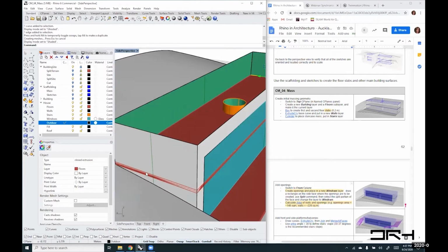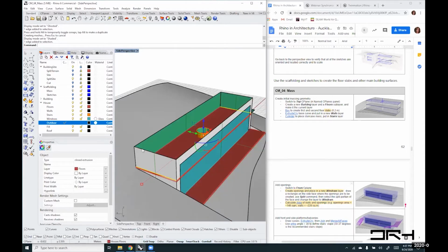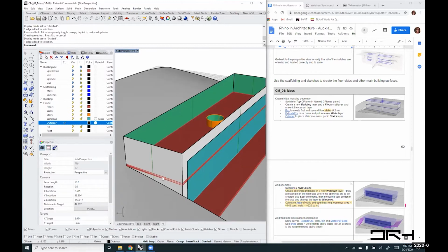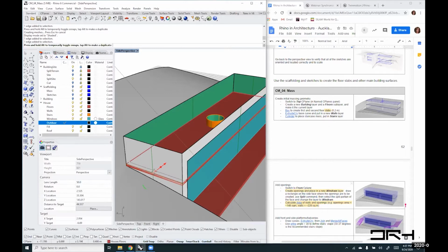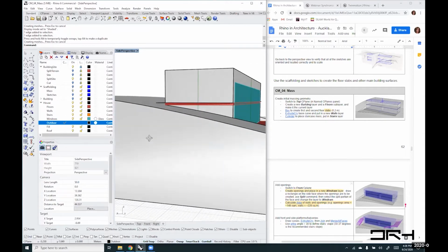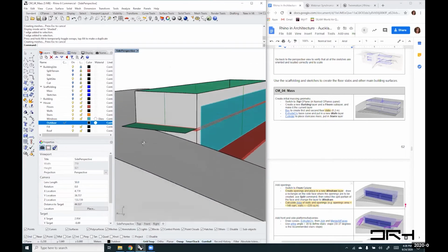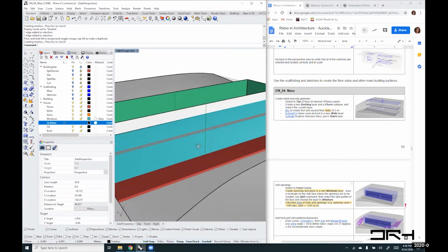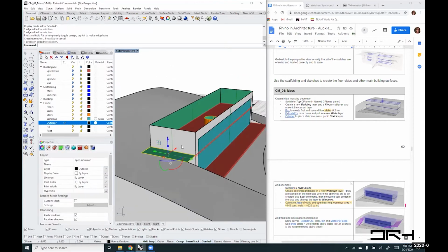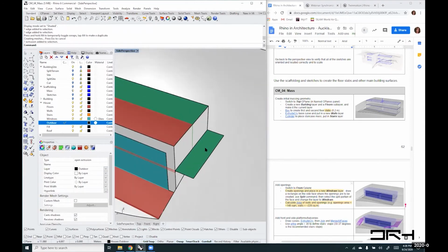So I'll do the same here. I'm going to go Shift Control down, and I think I was selecting multiple things. So Shift Control, and on the sphere in the direction of the red arrow, I'll just type 2 so that I know this is the kind of distance that I want to go for. And so that creates this part. You can see that it is green in both sides, and that means that the normal direction is pointing downwards.